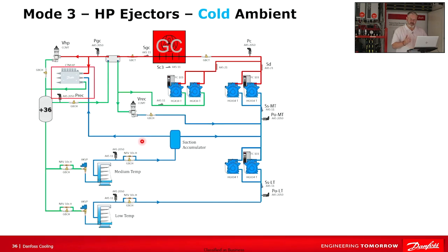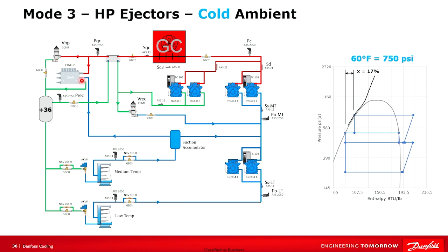So the benefit of that looks kind of complex. You wonder, well, what's the benefit? So we talked about parallel compression and what that does. So these will always be used, just food for thought. The ejector block is always used in conjunction with parallel compression. You can have parallel compression without the ejectors, but not ejectors without parallel compressors.